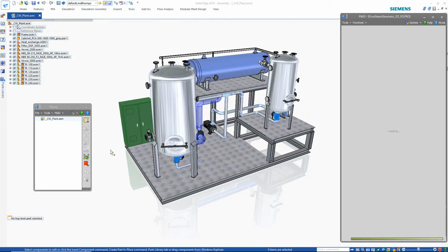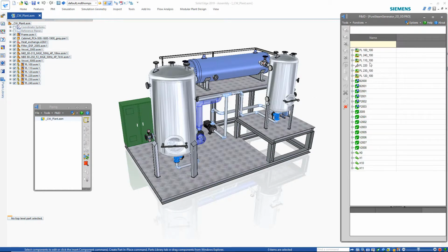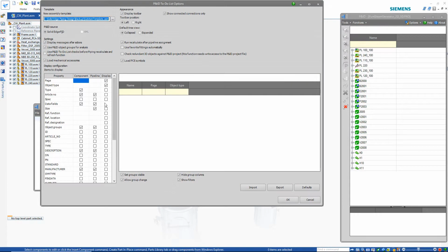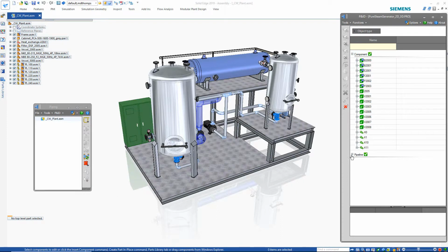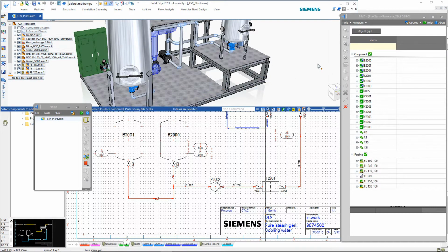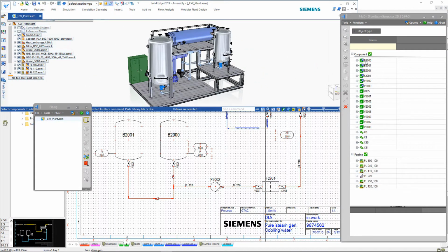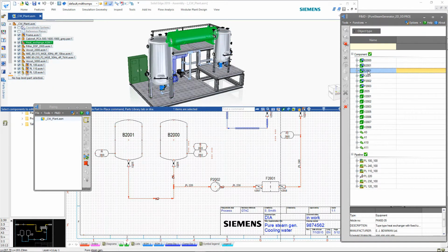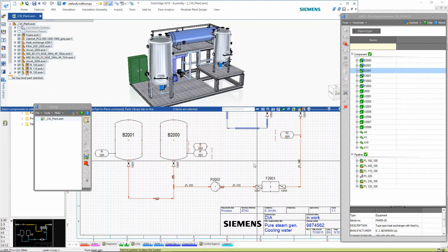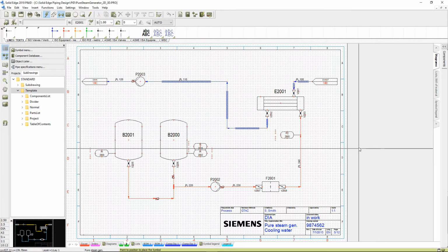To access the related 2D P&ID schematic, simply select to open it as well as the handy to-do list from within the piping dialog. The to-do list provides valuable feedback on what tasks need to be completed. The to-do list is configurable, for example, changed from a single list of components or filtered by component type, making it easy to find the things you're looking for. More importantly, it supports cross-highlighting in both environments. Selecting an object will highlight it in both the 3D model and 2D P&ID.